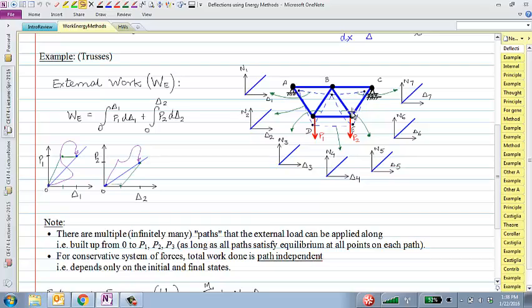And for trusses, I showed you last time that if you think of each member of the truss as a single spring, can we do that? Can I think of each member of a truss as a spring? Why or why not? Yeah, you can, because it's elastic material and you know that it's applied under tension. Okay, yeah. So for trusses, especially, each member is either in compression or in tension, right?